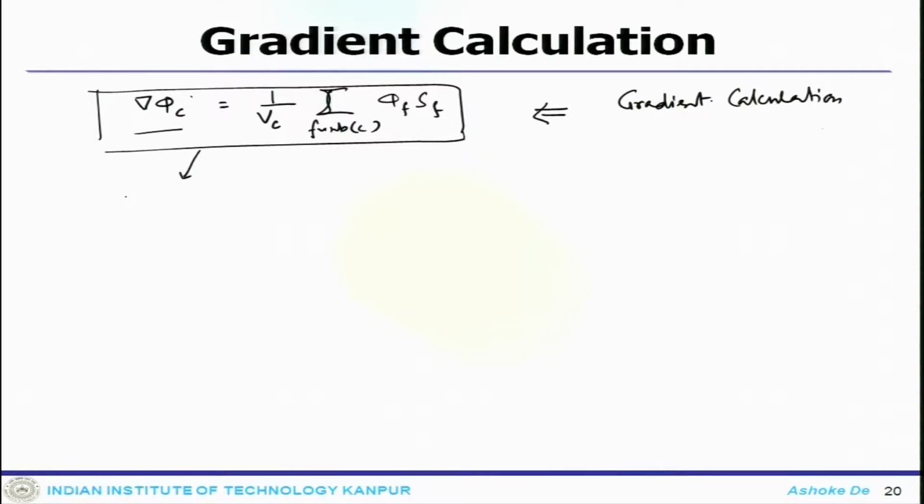One is using some sort of a compact stencil, where you have a correction term for your surface flux, which is like Gc phi c plus (1 minus Gc) phi f, where C is the particular element that one is concerned with calculating.